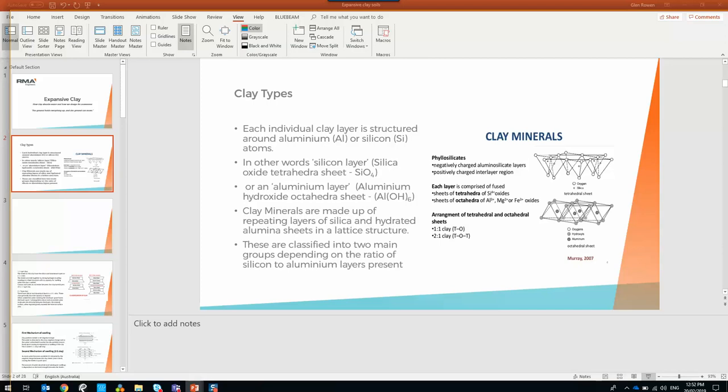The second one, I haven't seen it come back because it must have failed so badly, but if you ever see it surface, there's this guy that had this system where he used to scarify the ground up like he was planting a crop, saturate it for a week, and the theory being, oh, it's heaved as much as it's ever going to heave. So then he's got his screw piles in, then he put a suspended slab on it. There's a house out near the Toowoomba Showgrounds that's never been lived in because it stuffed up before they got the roof on.